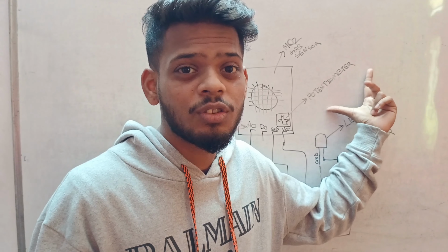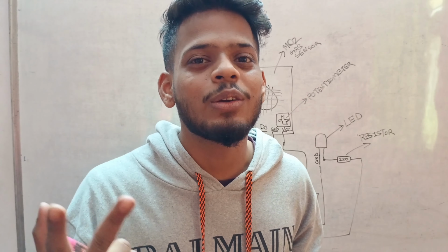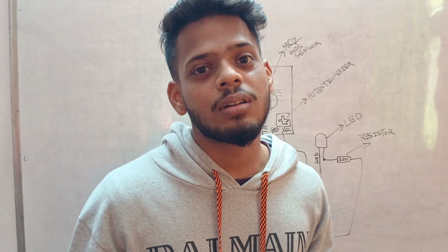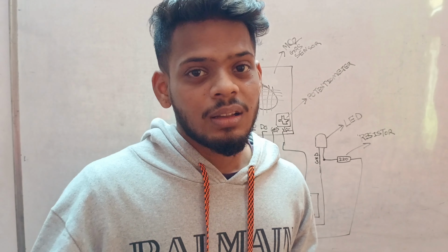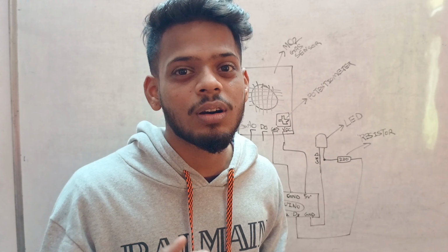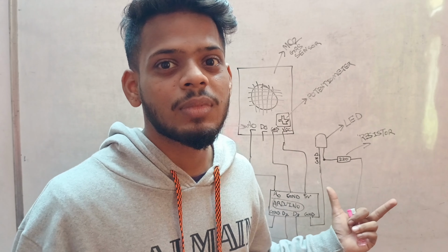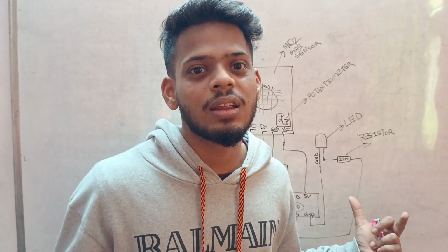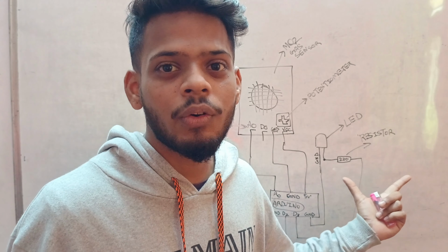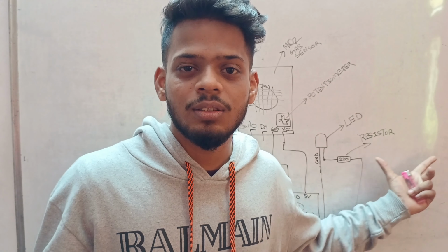We have completed the potentiometer. We have understood the MQ2 gas sensor. Now, LED and resistor. Why do you need a resistor? To light up an LED. We are dealing with Arduinos. LEDs aren't that safe to handle with Arduinos directly. Sometimes it may occur, we shouldn't say, but something bad may occur, like the LED might burst or any electrical failure would happen. So to avoid that, we will regulate the electricity, or we will use a resistor that is of 220 ohm.